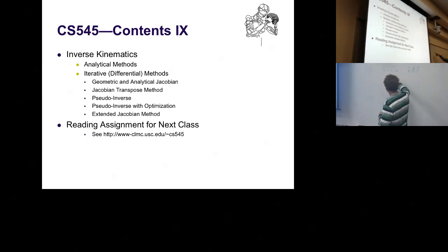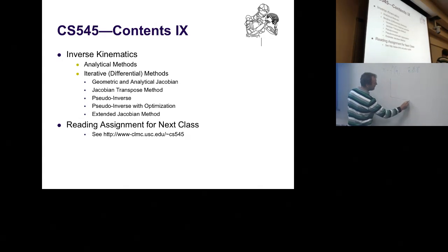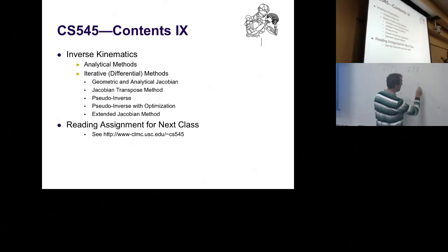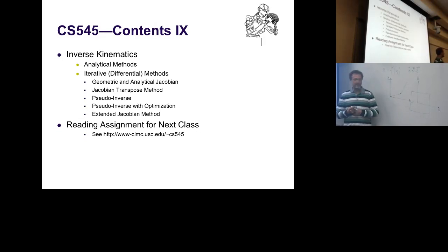Okay. What we stopped with last time was the interesting insight. If you take a 2-joint arm as an example, here is my favorite super trivial little example in an XY space. If you look simultaneously at its joint space, let's call this theta 1 and theta 2, the joint space is just a simple box which is as big as the range of motion. It has a max and min for every degree of freedom, that's it. But when you map this movement which you can do in joint space to this robot arm, it becomes this kind of convoluted weird space, and I just make it up right now. So this mapping is a pain.